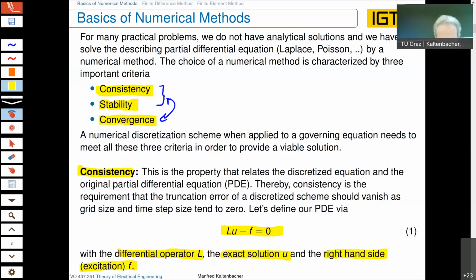So you write this down. I also write here simply that it could be minus the Laplacian of the scalar potential equal to the charge density. And then clearly, not written down, but we know you only get a unique solution when you also have correct boundary conditions. So we have to know along the whole boundary our boundary condition. That could be a homogeneous or inhomogeneous Dirichlet boundary condition where we prescribe the electric potential to be grounded, meaning zero, or to have any value, for example.